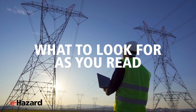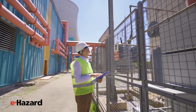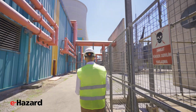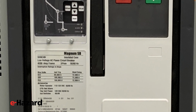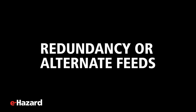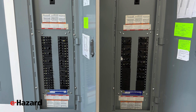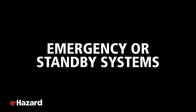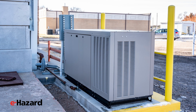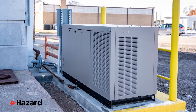What to look for as you read. Voltage levels at each bus or transformer secondary. This tells you the system voltage at that point. Breaker ratings. Ampacity tells you the circuit's capacity. Interrupting rating tells you its fault protection capability. Redundancy or alternate feeds. Some systems have 2 utility feeds or a tiebreaker between buses for reliability. Emergency or standby systems. Look for generators and automatic transfer switches, which appear when utility power fails.